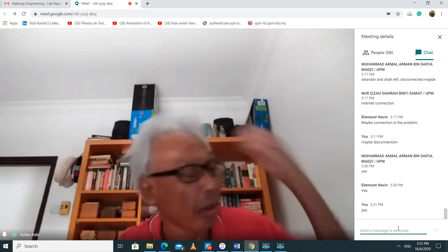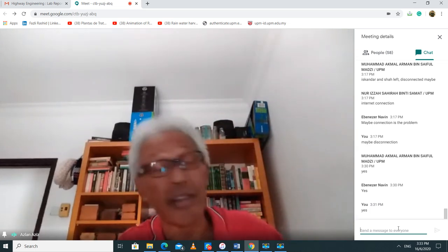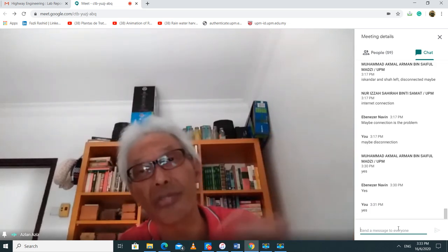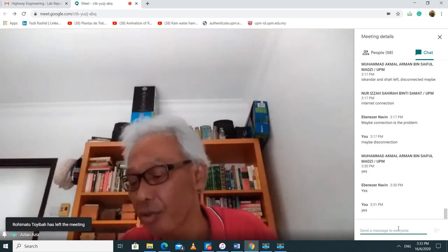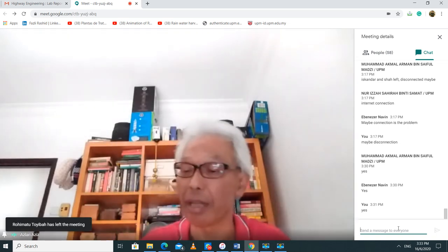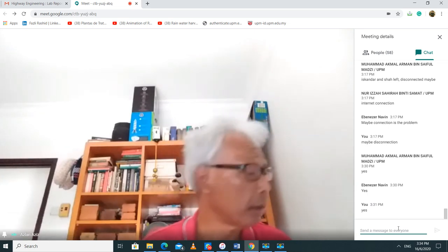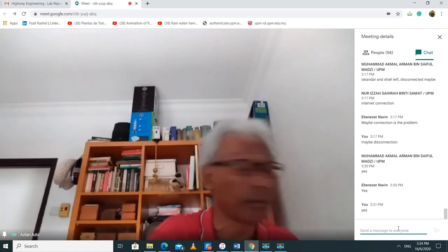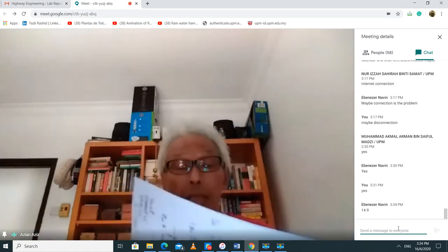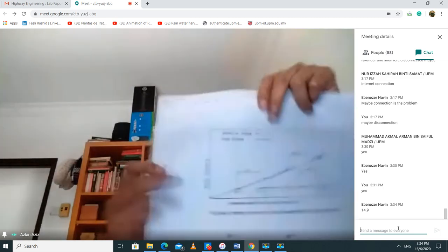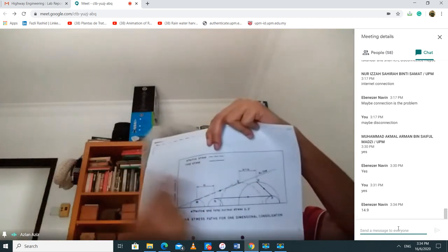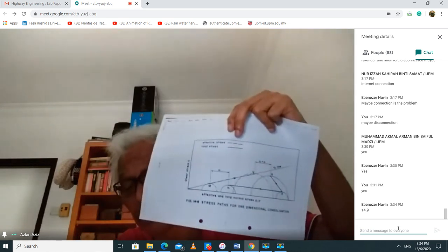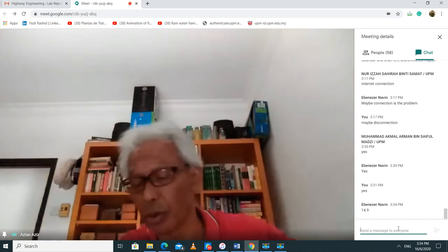You remember I said earlier on that this sigma H against sigma V, which is sigma 3 against sigma 1, is related to some K naught, which is a constant always. You will see that picture on page 14.9. You have that 14.9, right? The K naught line. See? This 14.9, the K naught line is a constant. It's just a line with a constant gradient. That M to Q.